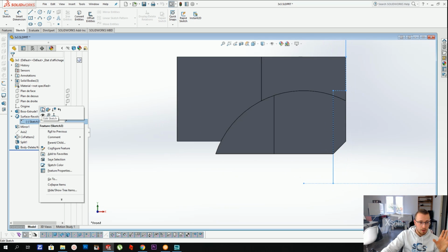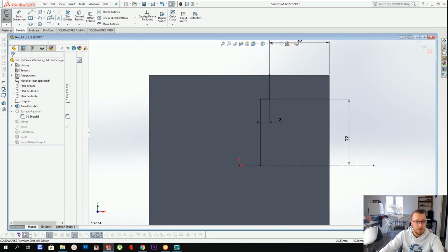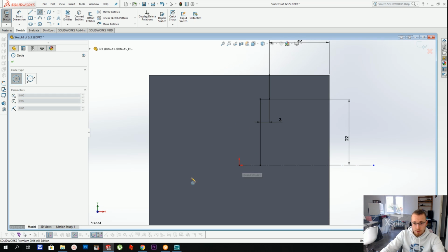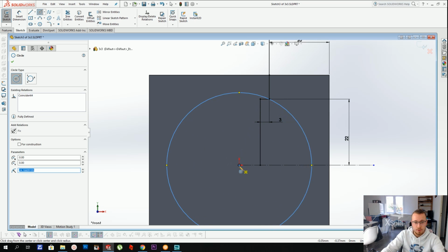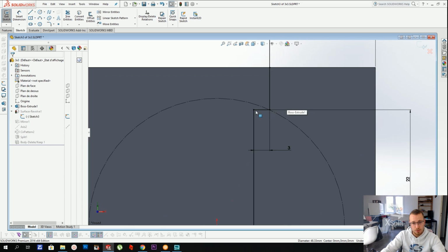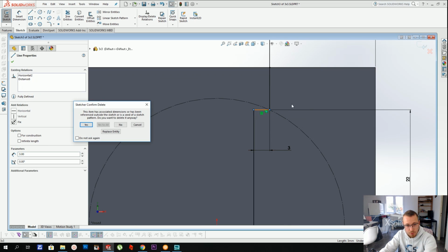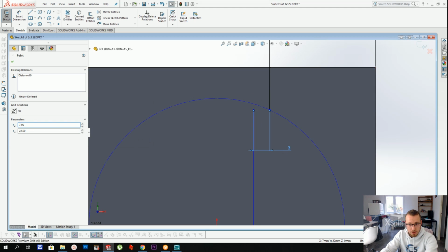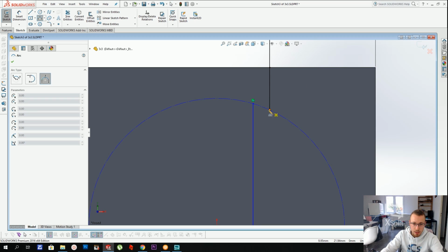So what I'm going to do now is I'm going to switch the cylindrical mechanism into a spherical mechanism. So on the original sketch of the surface that I created right there, you can create circles that go through the center, because this is, after all, a 2D sketch, so it's not a sphere, it's actually a circle. And you're going to remove the cylindrical part of the mechanism. That was the hook that we created. And you're going to make sure that this is on the sphere, and instead of using a line here to make the cylindrical mechanism, you're going to use an arc, a 3-point arc.